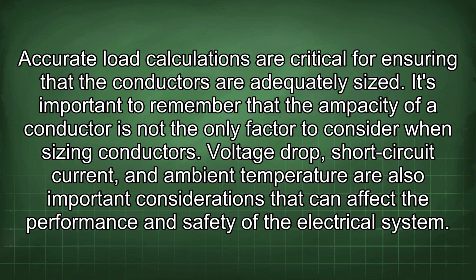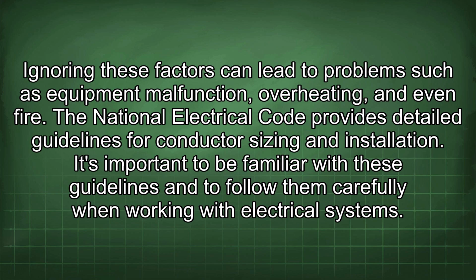It's important to remember that the ampacity of a conductor is not the only factor to consider when sizing conductors. Voltage drop, short circuit current, and ambient temperature are also important considerations that can affect the performance and safety of the electrical system. Ignoring these factors can lead to problems such as equipment malfunction, overheating, and even fire.